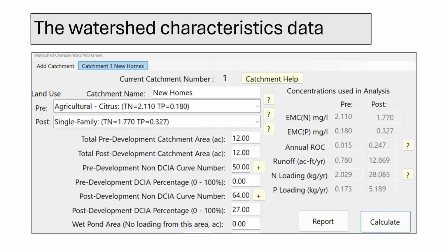However, if a wet pond were the agreed-upon solution, and both the review agency and the plan preparer were in agreement, then the appropriate wet pond area could be entered into the system. It's also worth noting that there were no additional loadings from pumped or groundwater discharges to account for in this specific case.